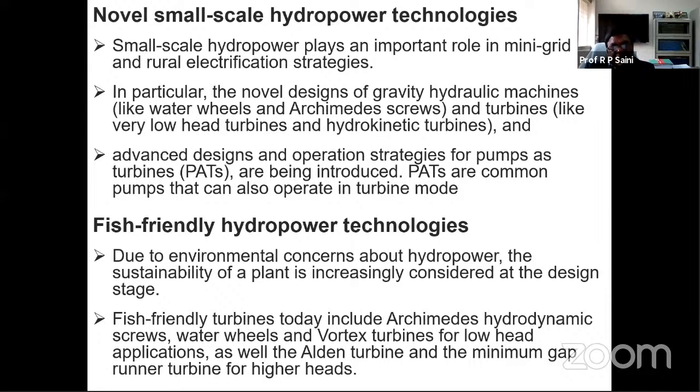But hydro is almost 1,000 times denser. You know, it's 1,000 kg per meter cube, and there it is 1.2 kg per meter cube. So that means even at a very low velocity, because if I am talking about the potential energy, it's okay, mgh, but here it is kinetic energy, purely velocity energy, half mv squared, half rho A v squared, half rho A v cube.